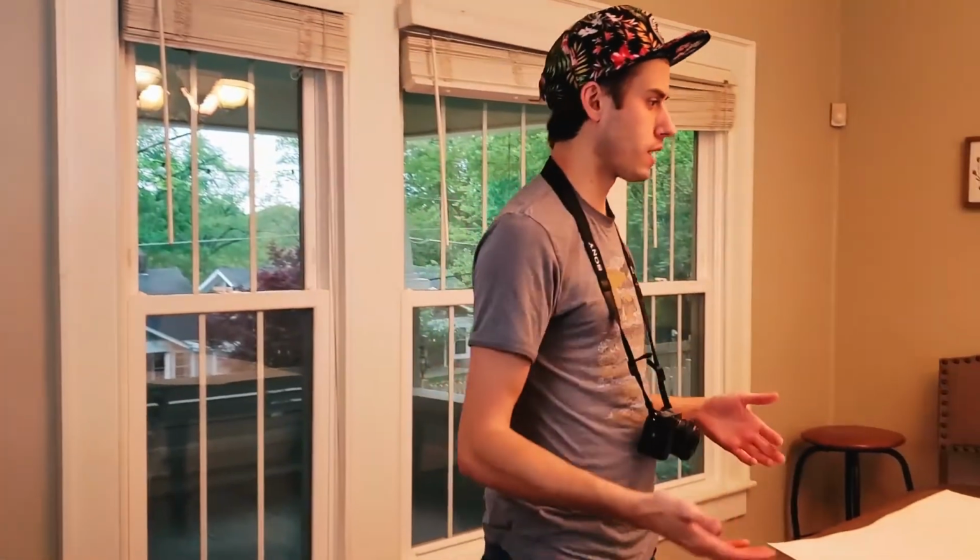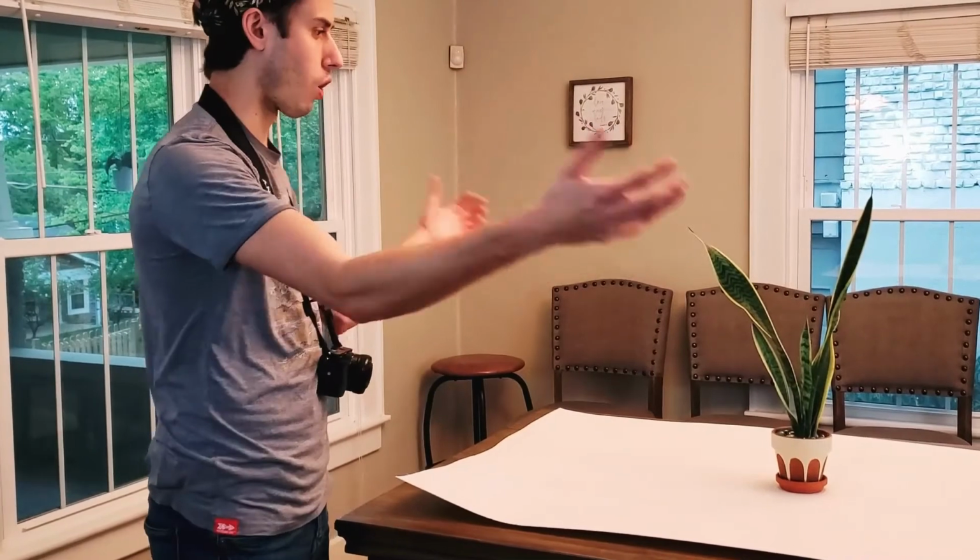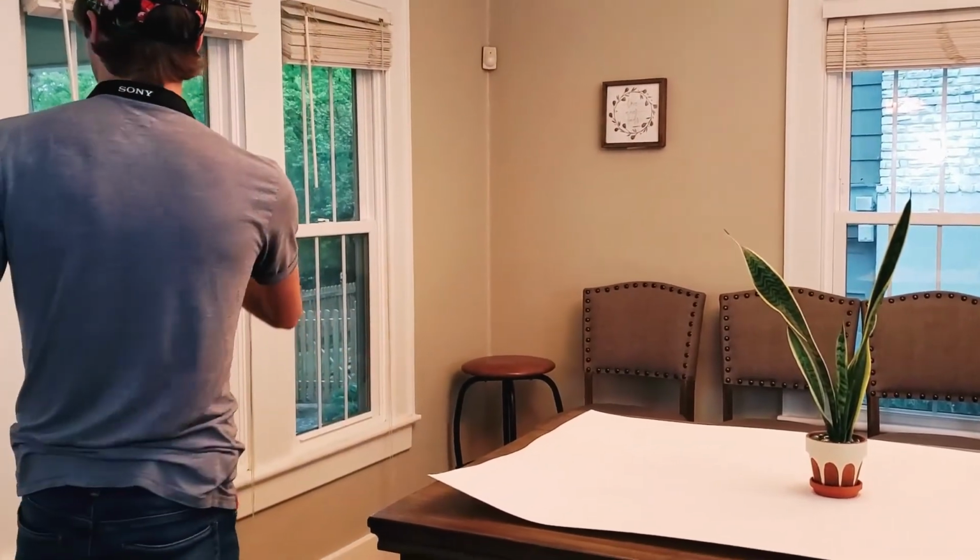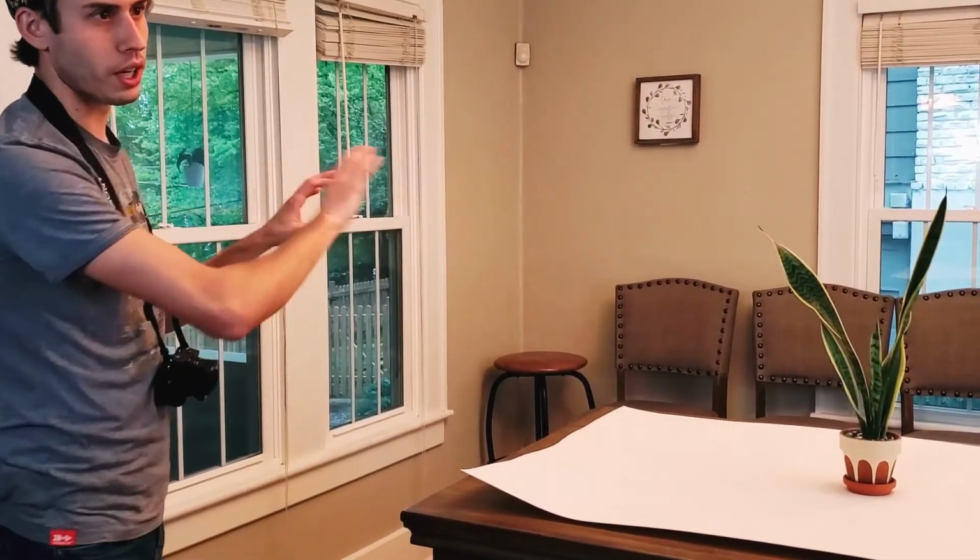And the reason I'm doing this is that I can get even lighting on my object, so I have lights coming from all sides, and then I'm in a well-lit room with plenty of windows, so I'm getting a lot of that diffuse light coming in, especially if you're trying to do this outside, it's really important that you don't have any sunlight coming in, creating shadows, because those will be in your model. We want to be able to light our model in the 3D software. So having the lighting coming in, it just won't work for you.